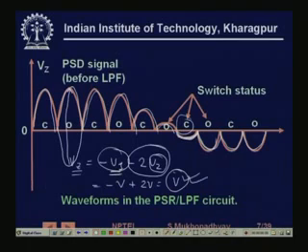So now the switch is closed when the wave is negative. So the same thing is happening here. It was closed when the wave is positive. Here there is a phase inversion, but the sine wave carrier is still positive here. Therefore, the switch becomes on. So the switch gets on and off according to the carrier wave.